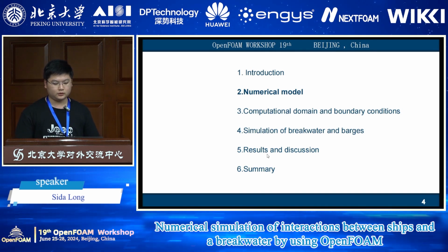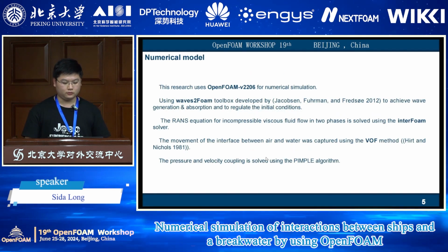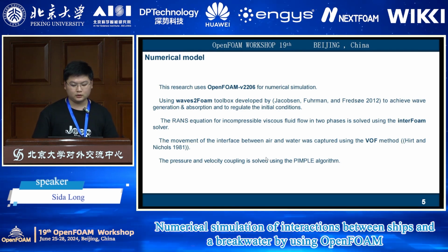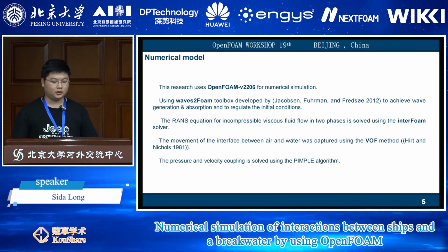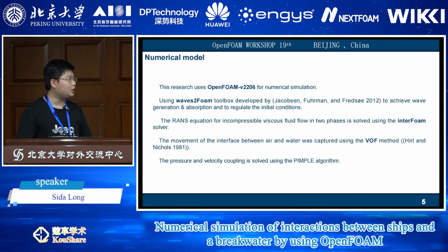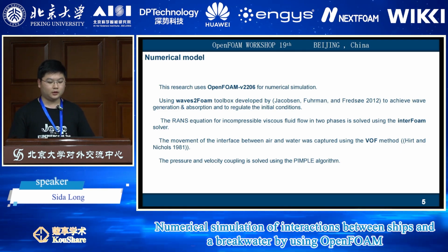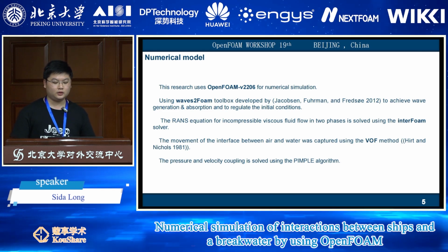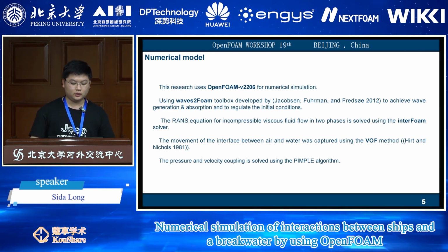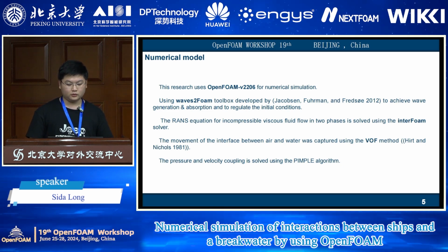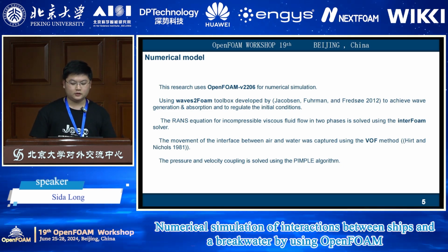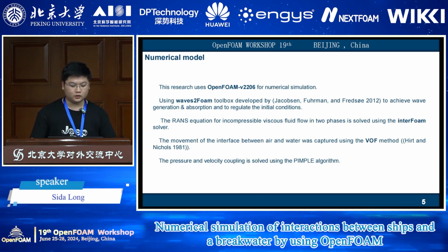The part two is the numerical model. The research uses OpenFOAM version 2206 for numerical simulation, and we use the waves2Foam toolbox to achieve wave generation and absorption and to regulate the initial conditions. The governing equations for incompressible viscous two-phase fluid flow are solved using the interFoam solver.